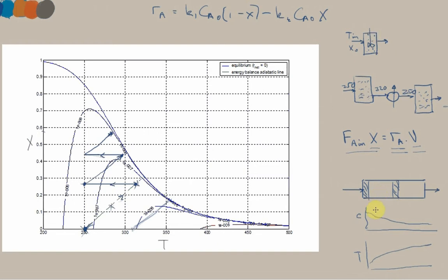And this can be significant because, and we've mentioned this point many times before on the course, this means there are regions in the PFR where the rate will be higher than other regions. And this can result in a significantly lower overall required volume for a plug flow reactor as compared with the CSTR.